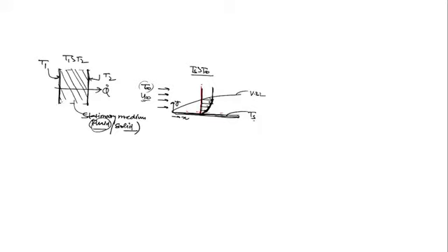No? It means if this is the axis, then here the temperature is Ts, and as we are moving in the y direction, the temperature decreases, like this, and there is some thickness where the temperature reaches T infinity. So this was the velocity one, this was delta. Delta is called the velocity boundary layer thickness. Now, this is called delta Th. What is delta Th? This is called delta Th, the thermal boundary layer thickness.